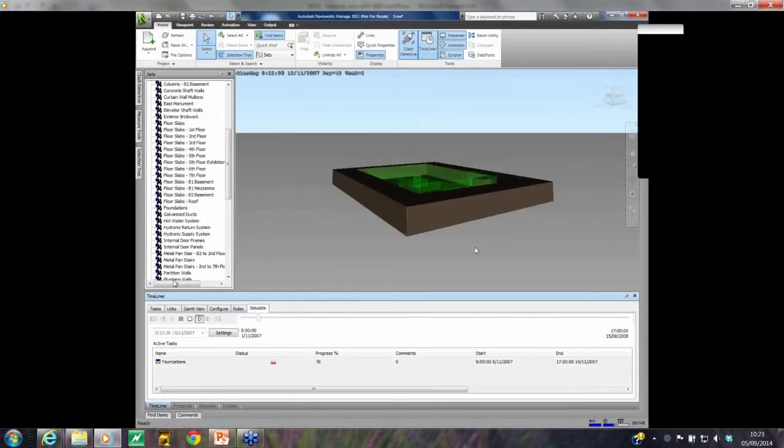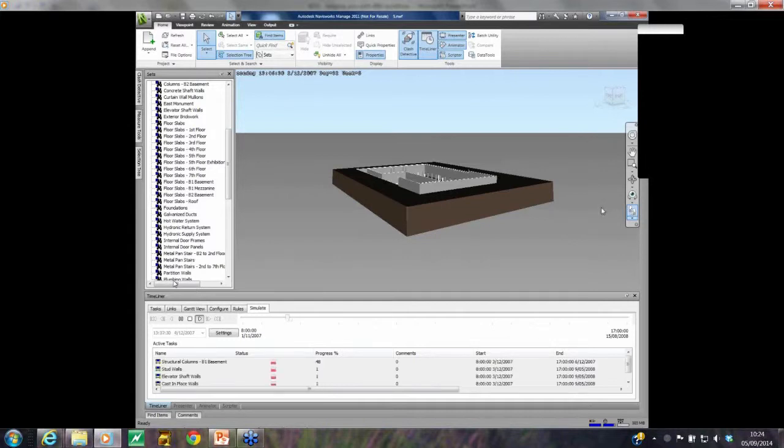And then we ask it to do a simulation. Now basically what's happening, we're asking the software, Navisworks, to run the timeliner. We're asking it to look at the events which are linked to the project management software and then visually display what part of the model is associated to that task. And as we'd configured the physical appearance, we will see in real time something which is new, which was being constructed, highlighted transparently in green.